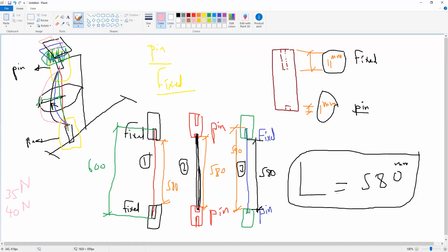This means that the critical load will be somewhere between both of them, because you cannot exactly get the buckling load using this type of testing, okay? Because you have only 5 Newton increments. If the load is between the two 5 Newton steps, then roughly we will assume that the load is something between 35 and 40.